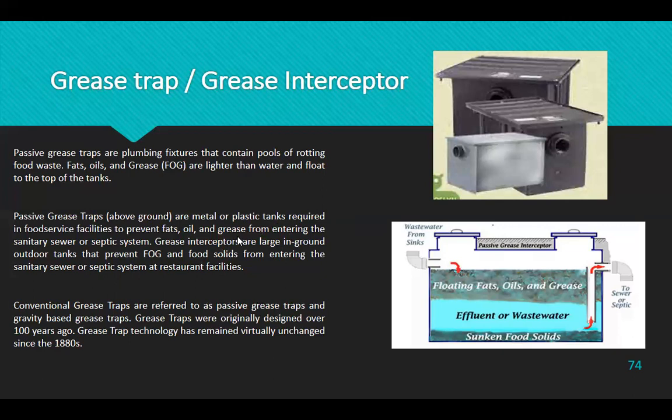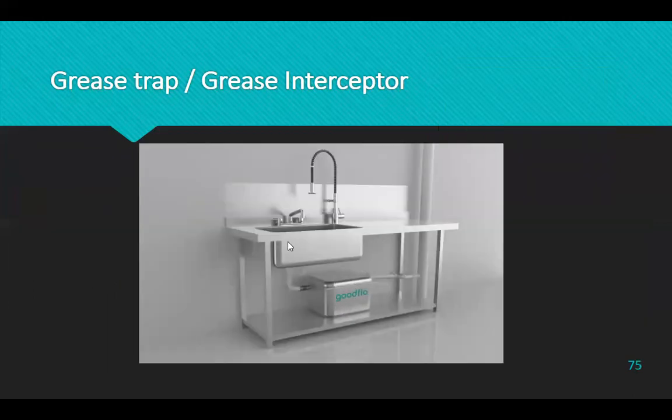There are two kinds. You will see tables with pictures of the units. For the small one at the kitchen sink, normally the requirement is 15 gallons per minute. That is hydro-mechanical, not gravity. For gravity, the unit is in gallons, the picture unit equivalent is in gallons. For hydro-mechanical, it is in GPM. So for GPM, 15 GPM for the kitchen sink, in SM they require that, and 7 GPM for hand wash. So this is the grease trap. When you wash here, it's simple: the oil parts will float, so what you drain is just the clean water.